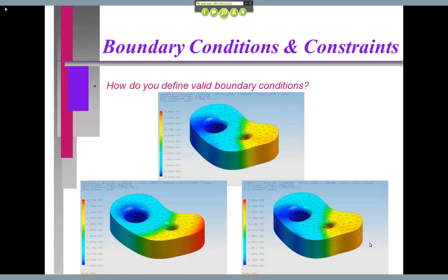So when it says, tell me what the loads are, you have to think about the magnitude and its direction. And whatever its magnitude and direction, you have to apply it where? At the nodes. So the CAD system says grab an edge, grab a surface. It may allow you to grab edges and surfaces, but if you've got a 10,000 Newton load, and you grab the edge and you're applying that load to the edge, what is it doing?